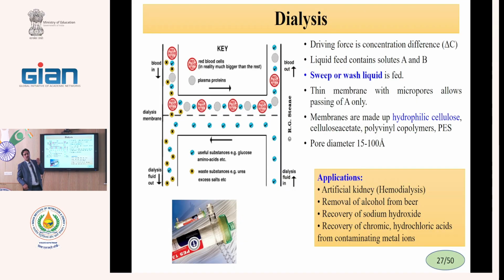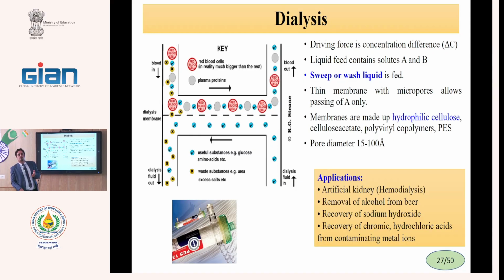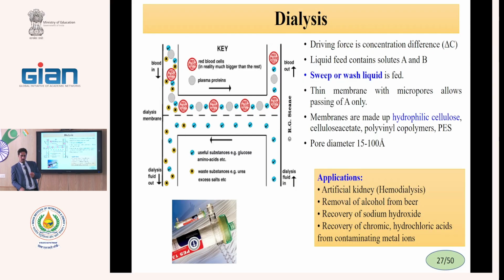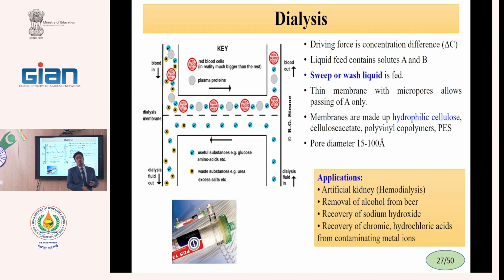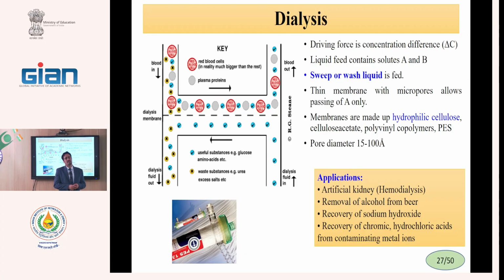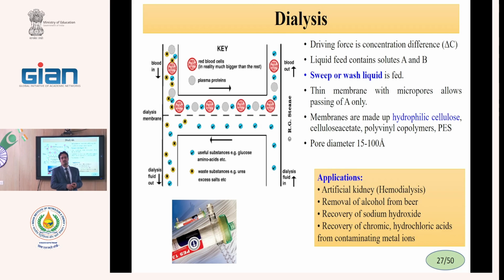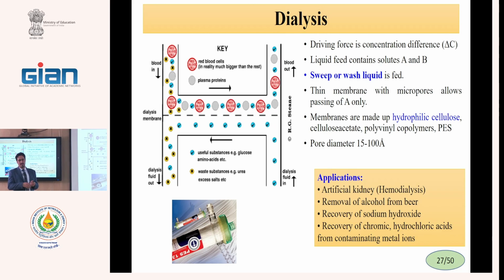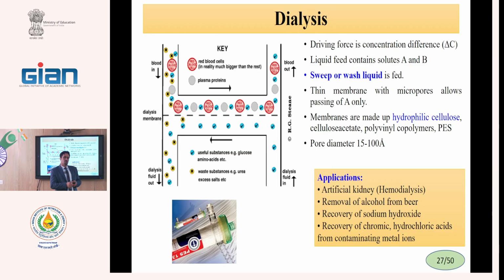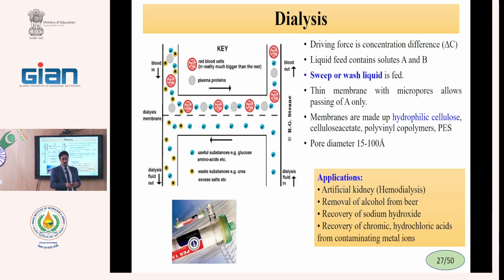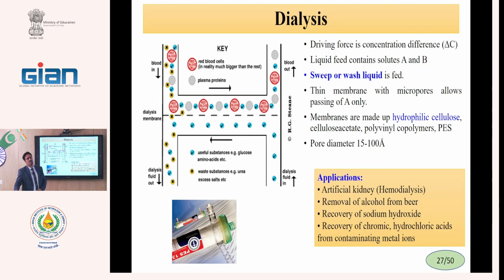When we want to use hydrophilic polymers for PV, we usually use polyvinyl alcohol. Polyvinyl alcohol is a hydrophilic pervaporation polymer, and to reduce the swelling, we usually cross-link the PVA for separation of water. For separation of DMF, you must use PVDF or PTFE membranes, non-porous membranes.